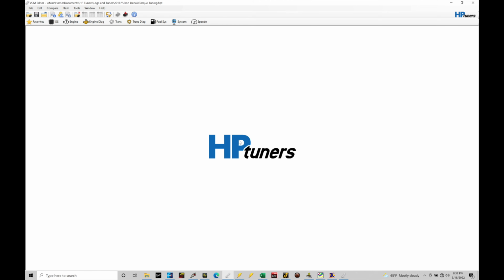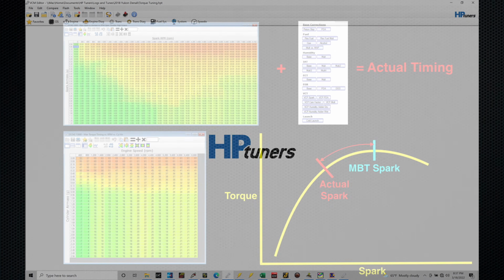That all hinges upon a whole bunch of things riding around what's known as maximum brake torque. So the three different variables that can affect our maximum brake torque that we have control over are fuel, spark, and variable cam. Let's take a look here first at spark timing and how this is going to fit into the picture. So let's just say we have X amount of air mass coming into the engine, doesn't matter what the number is. That amount of air mass needs to be figured out and how it relates to torque. We figure out what that relevance is going to be, airflow to torque, based on the spark timing first, then our EQ ratio, and then our variable cam.